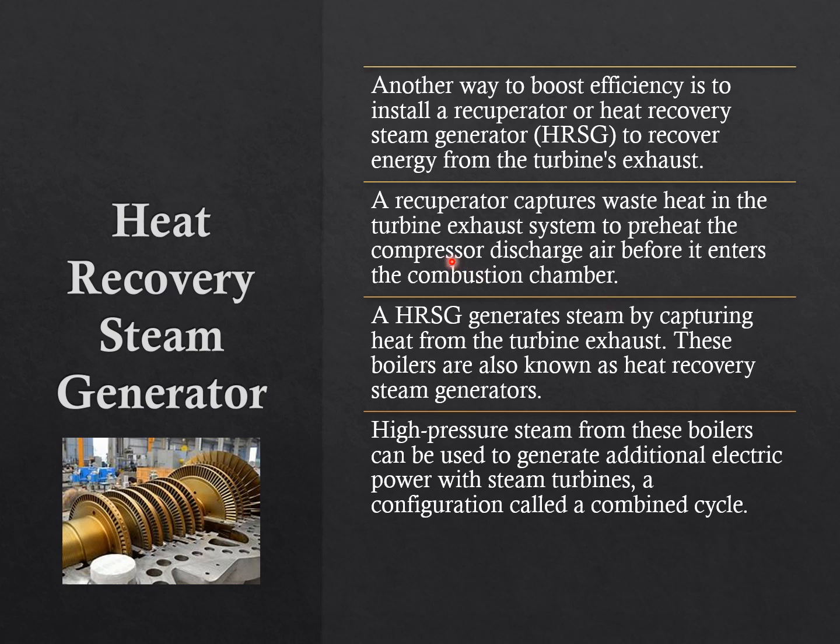Since you preheat the compressor air, you don't have to burn as much fuel mixed with the air to heat it back up. So it's kind of like recycling: we capture the exhaust heat and use it to heat the air before it ever gets into the chamber.